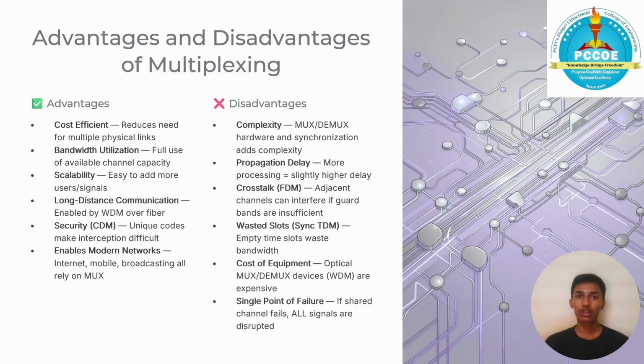On the disadvantages side, it adds complexity in terms of hardware and synchronization. There is crosstalk in FDM if guard bands are insufficient, synchronous TDM wastes bandwidth due to empty slots, and WDM is expensive. And if the shared connection fails, all signals are disrupted at once.